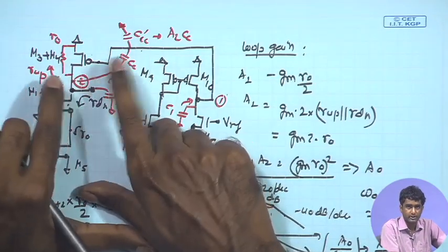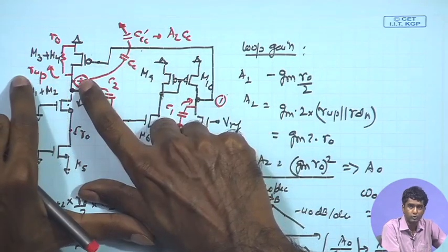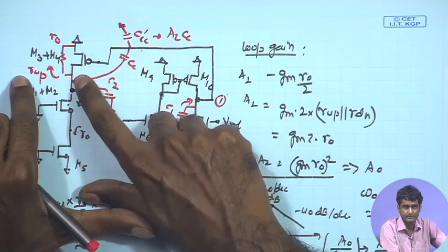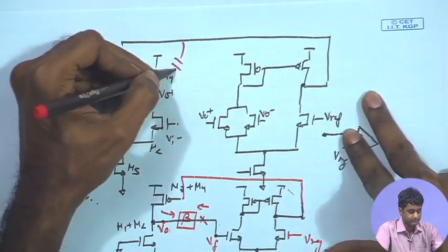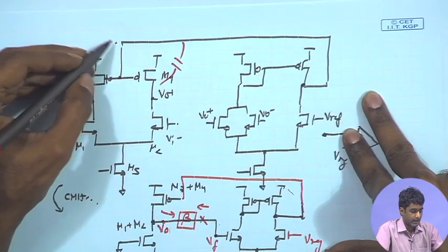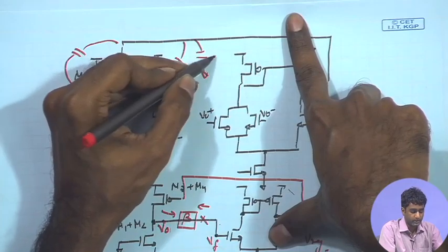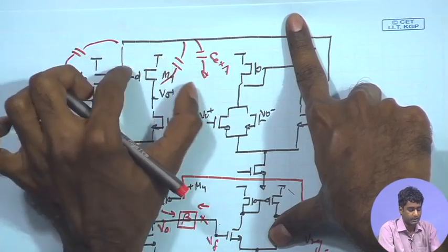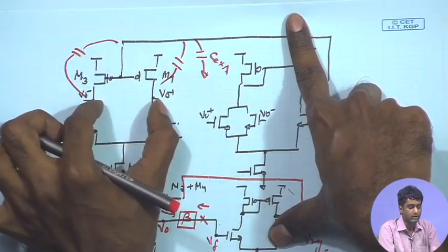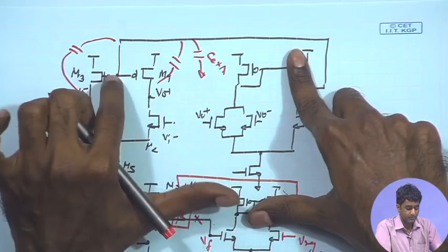So, in the actual circuit, this CC will have to be connected between the common PMOS point and the two differential nodes separately as per this scheme, and that would mean that both these differential nodes, where we are putting this CC, are seeing an effective capacitance over here, which is CC times A, the gain of the common mode half circuit from the input point to the output.